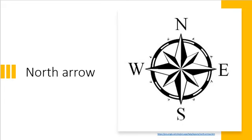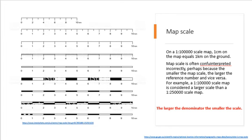A north arrow maintains a connection to a map frame and indicates the orientation of the map inside the frame. When the map rotates, the north arrow element rotates with it. Map scale refers to the relationship or ratio between distance on a map and the corresponding distance on the ground. Always be careful that the larger the denominator, the smaller the scale.